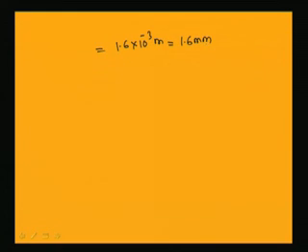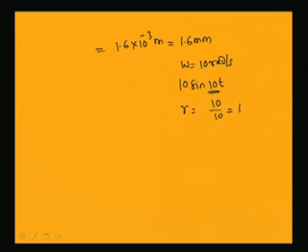And in the second case, when omega equal to 10 radian per second, you have applied a force of 10 sin 10 t. So, in this case omega equal to 10. So, your r becomes 10 by 10, which is equal to 1. So, you can observe that in this case your magnification factor x by x0